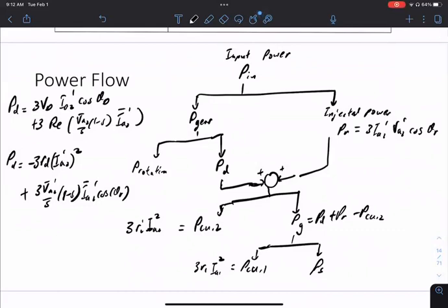So you have to solve a nonlinear set of equations in practice to make this work, because your control variables are here. And this is an equation that's not so nice, especially with this thing here and this I again here, with complex numbers all involved. So in practice, going backwards is not trivial to do. When we do calculations, we go this way, but the thing to remember is that to operate this kind of turbine, you actually need a fair bit of real-time computation for this to work. And you're always computing backwards in practice. Okay, yeah.